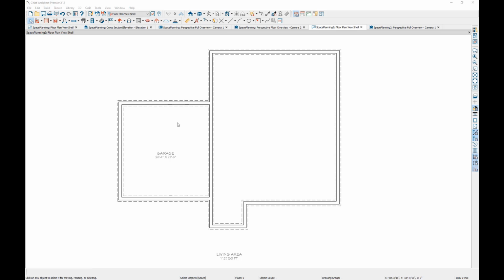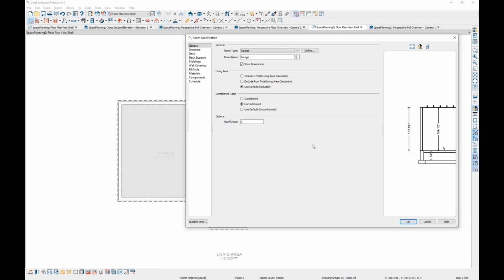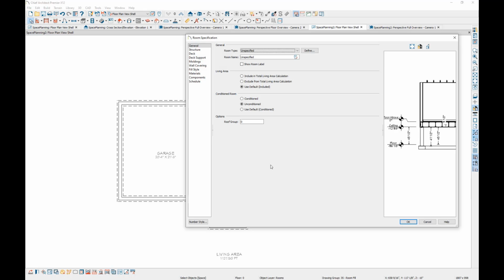It knows that I have a garage room based on what was in the primary floor when I generated the foundation, so it gives me some parameters here. It automatically makes it a 24-inch long stem wall. In the primary space, it uses that longer stem wall depth that we specified. And there's probably a couple things here that I could do differently.